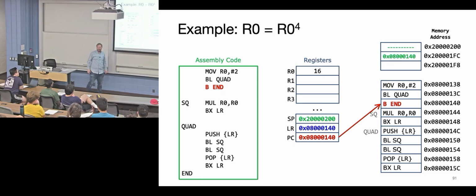Okay. So I guess you could have said, because you never used R3. But don't you always have to preserve it to make it ABI compliant? Right, you always have to preserve it. So you can preserve it somewhere else, but you might have to preserve something else. You could go and put it, I guess, in R3 and put it back. It's just that's not the convention.